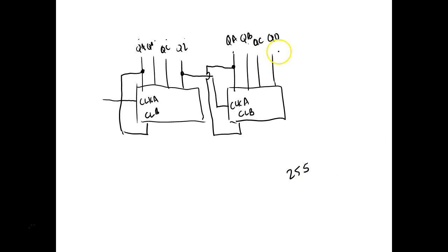But your propagation delay would be set by this guy. So this would decrease the speed of your count a lot with these ripple counters, right? You understand? And if I needed to count further, I could add another one, take the D output of this one, feed it into that one, and I'm not going to draw all the rest of them, right?